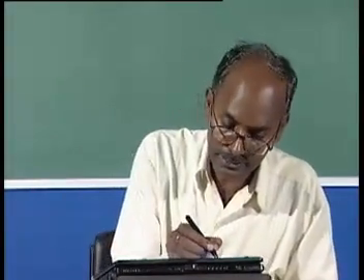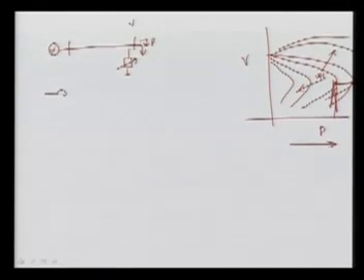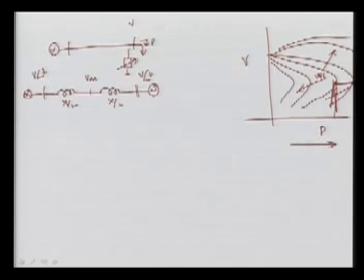Again we will consider the same system, that is, a line that is partitioned into two parts. Here is the source, here another source, and we have the midpoint voltage, that is x by 2, here x by 2, and this voltage has angle delta, here this is angle 0. Here we are putting a compensator in the middle of the line.